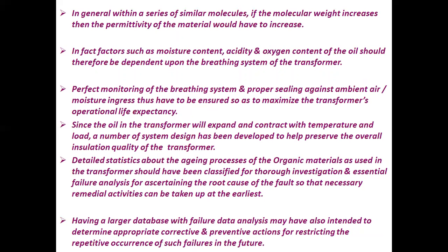In fact, factors such as moisture content, acidity, and oxygen content of the oil should therefore be dependent upon the breathing system of the transformer. Perfect monitoring of the breathing system and proper sealing against ambient air or moisture ingress thus have to be ensured so as to maximize the transformer's operational life expectancy.